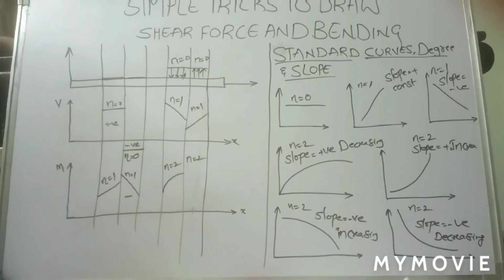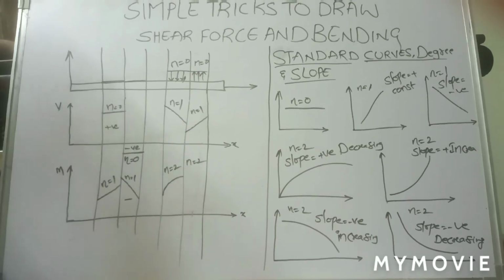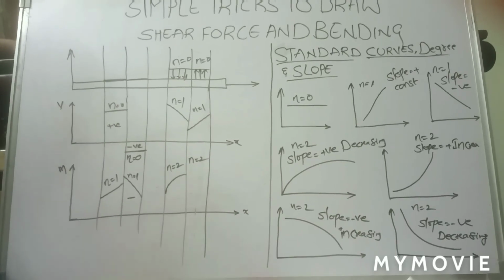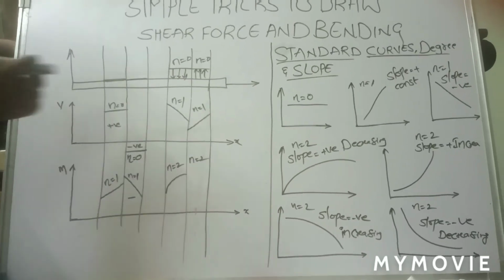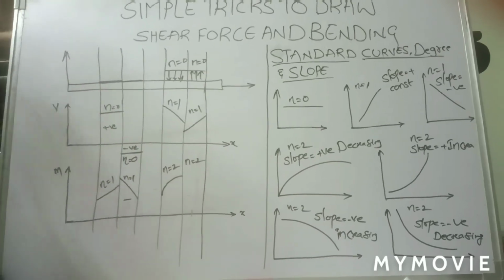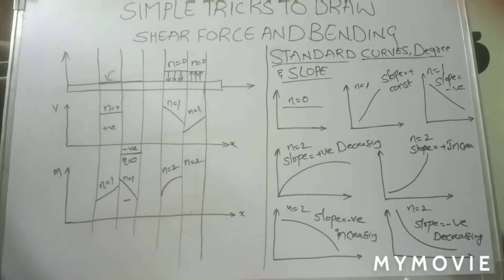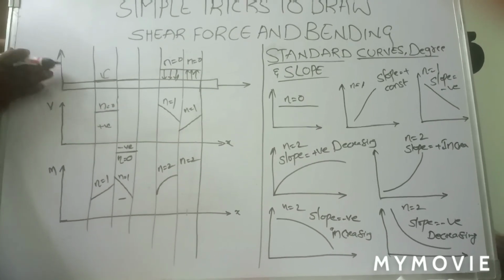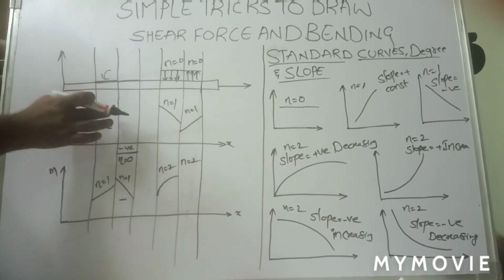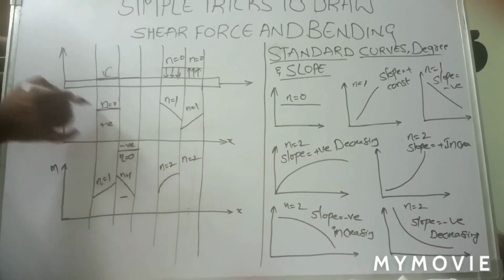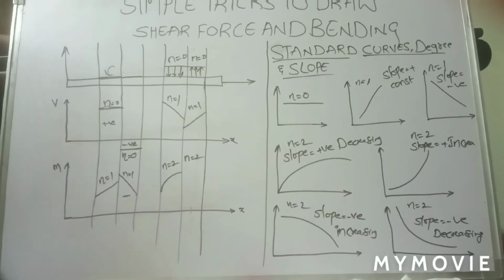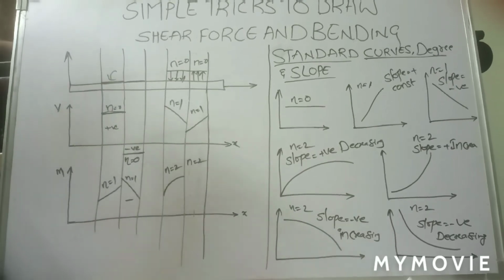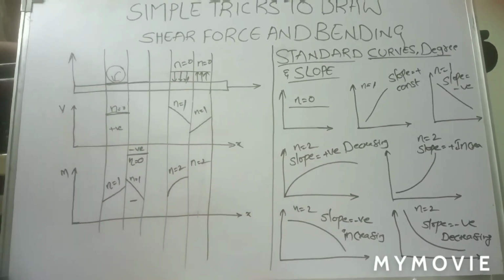Please observe that whenever you have no loading condition or a constant loading condition, the shear force diagram is constant, that means a straight line. So in a beam with a constant load, observe that immediately in the shear force diagram we have only a straight line. Remember this point: you will get simply a straight line whenever in a beam you have a constant load.